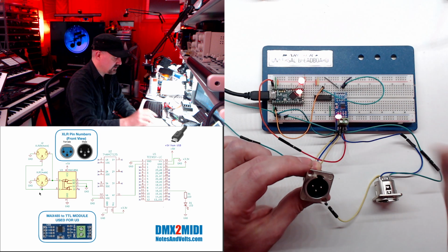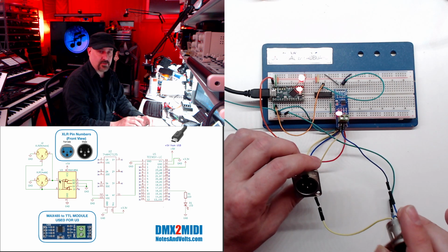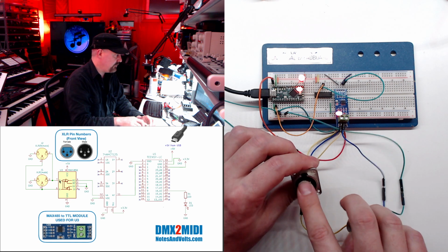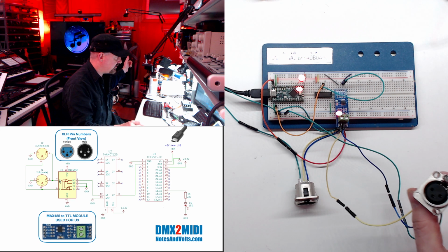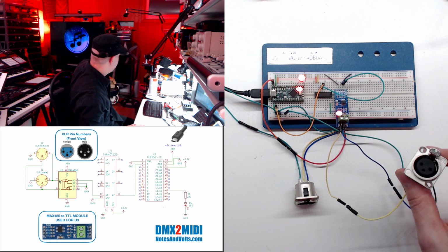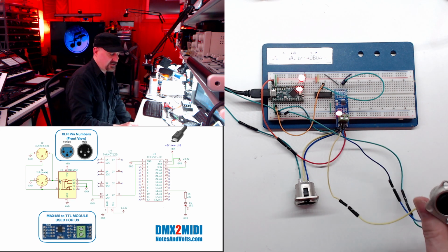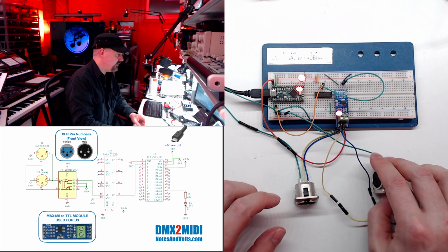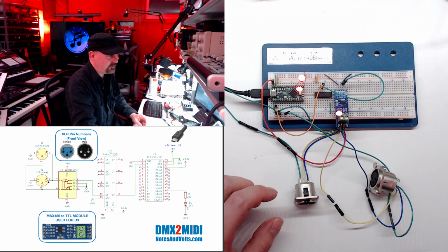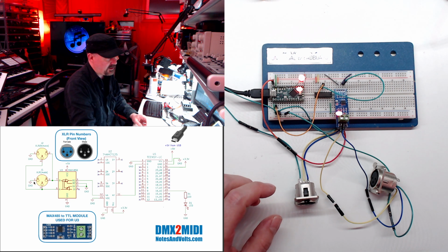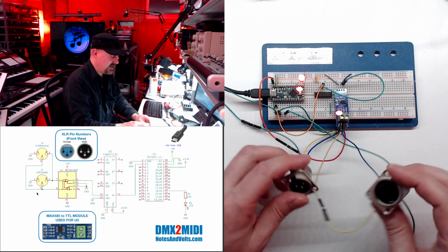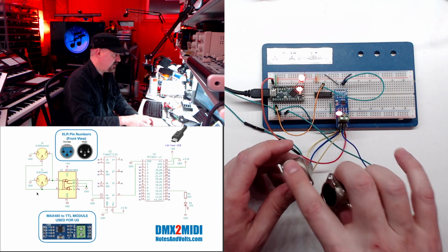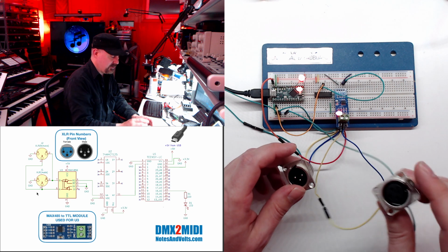is our system ground. A lot of times when you're running DMX lighting, you're going to have your input in here and then an output jack that's going to continue the signal along so you can run it to your other lights. That's what we've done here, and all we've done is wired the jacks in parallel. So pin 2 on the input goes to pin 2 on the output, and pin 1 and pin 1, and so on. Just wire the jacks together, and you'll get your input mirrored on the output.